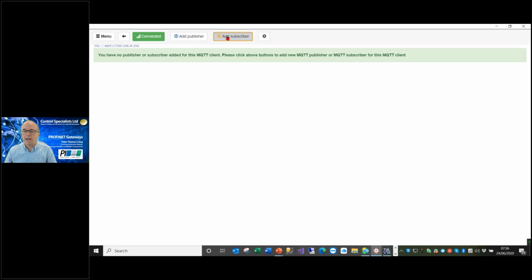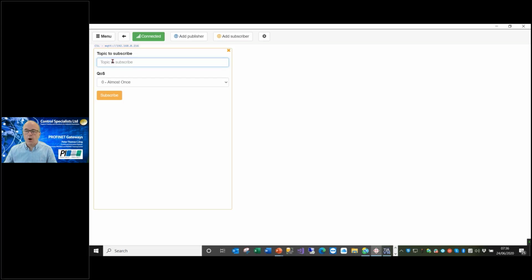So if I click on subscriber, what I have to do now is type the topic. Now, basic MQTT doesn't have a browsing interface, but if I type in, for example, that, which was one of the topics, and then I subscribe to it, then hopefully after 10 seconds, we're going to see the PLC publishing a topic.